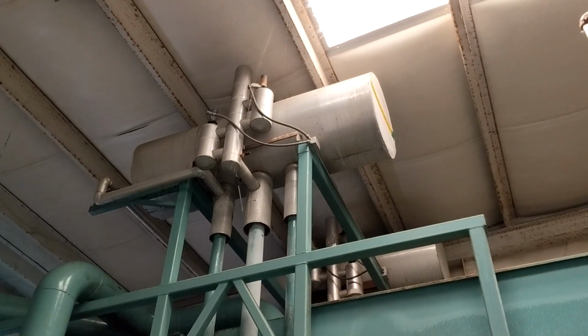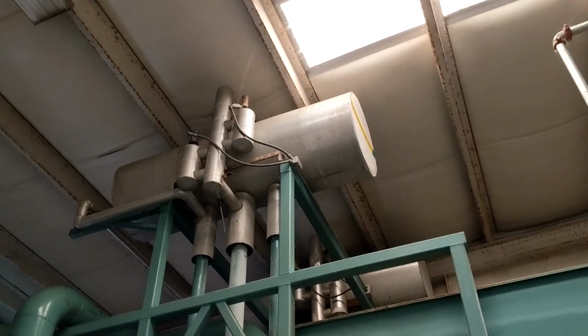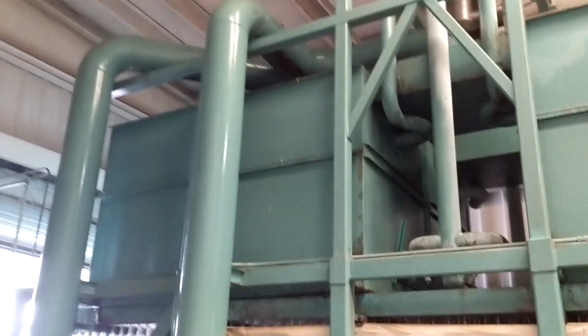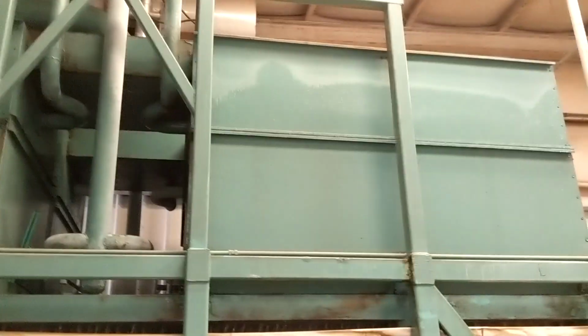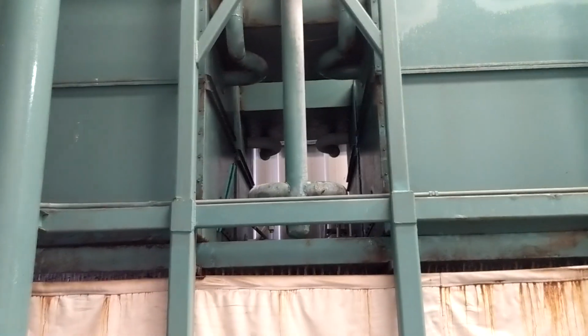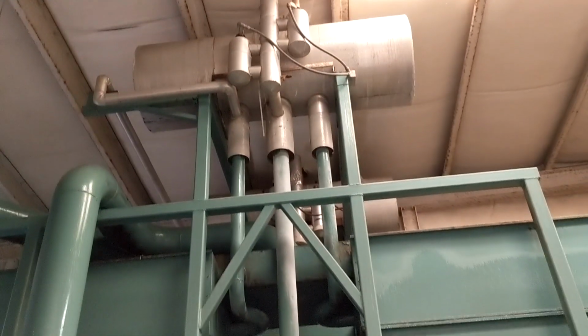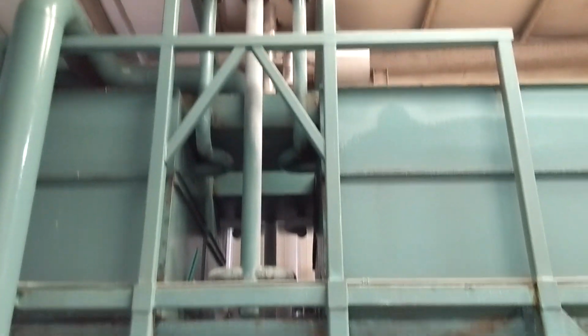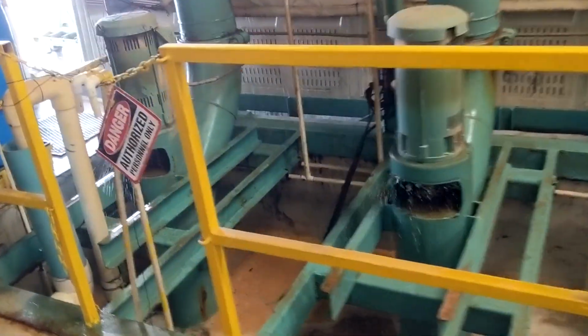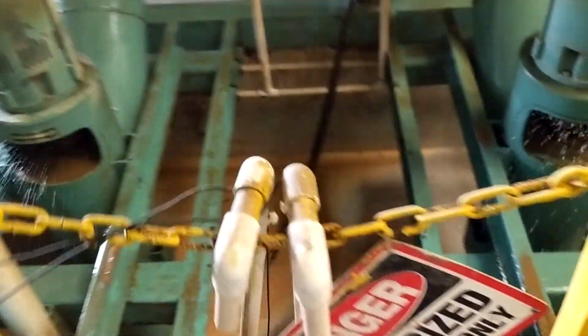In a hydrocooler, freshly harvested produce is rapidly cooled by spraying cold water over an evaporator containing cold liquid refrigerant. The chilled water then enters a distribution pan so that the cold water is evenly distributed over the produce. As the produce passes through the cooling chamber, typically on a conveyor, the water absorbs heat from the surface of the produce, quickly reducing its temperature. The cold water is constantly recirculated and recooled to maintain the desired low temperature.